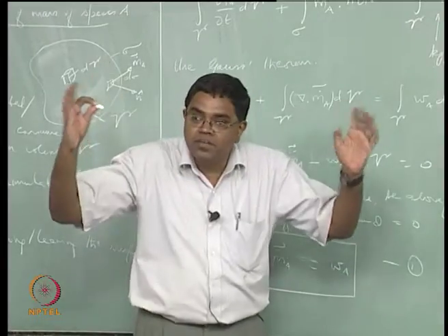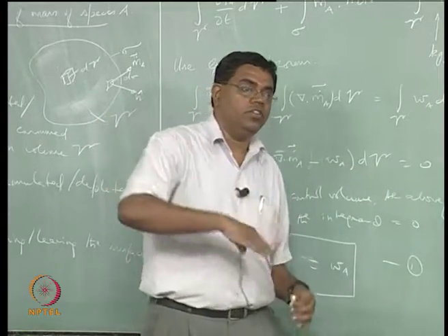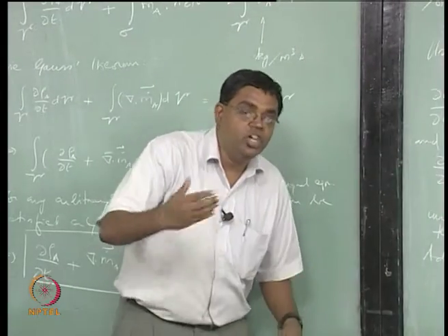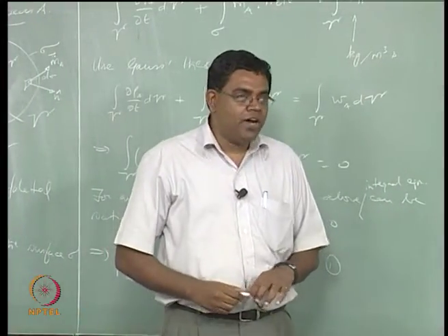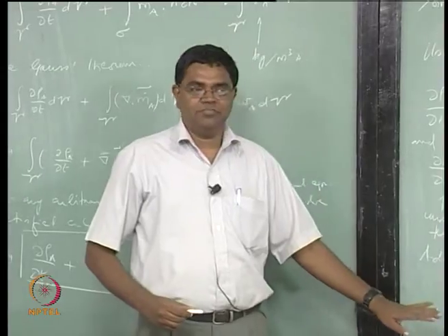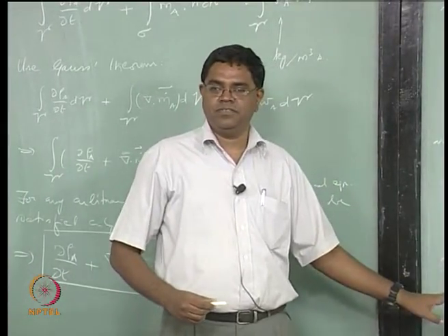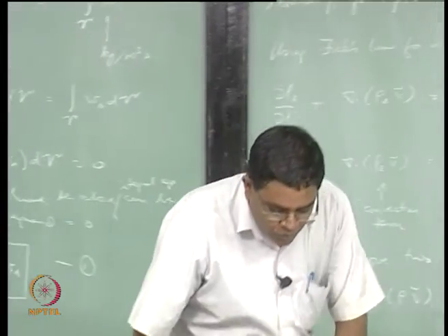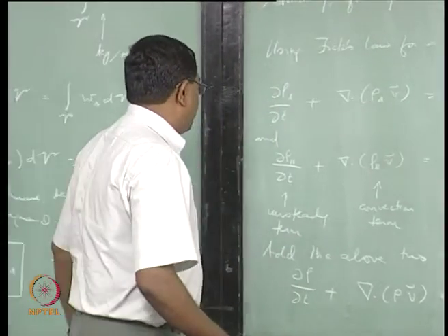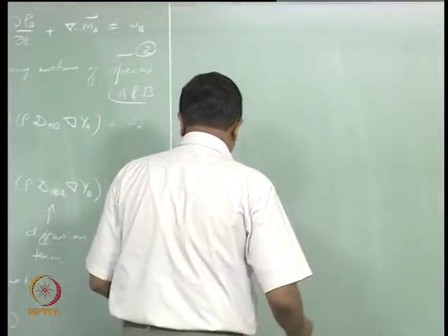As far as the mass conservation of the mixture, you will find that there are effects in the energy of the mixture and so on. But as far as the mass of the mixture is concerned, it didn't matter that you had a multi-component reacting flow. Isn't that kind of interesting, right? So you get back your mass conservation of a mixture as if it's a non-reacting single component situation.